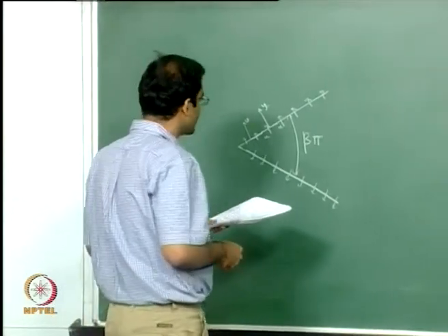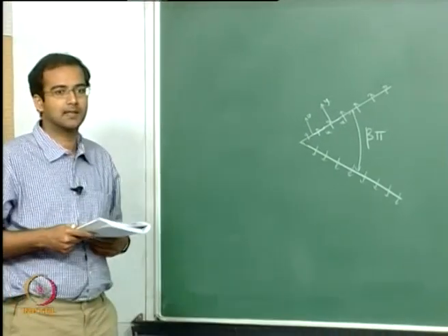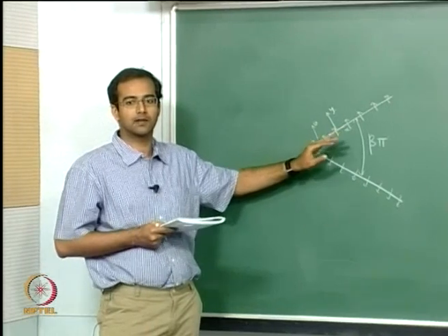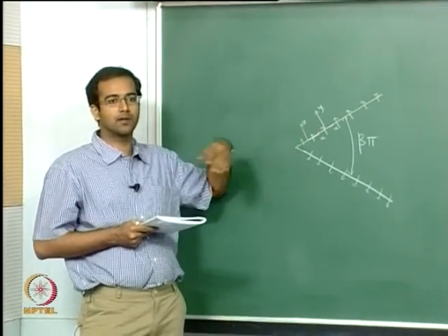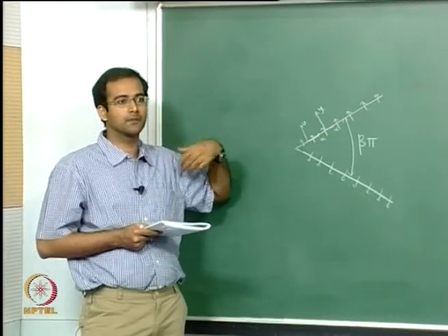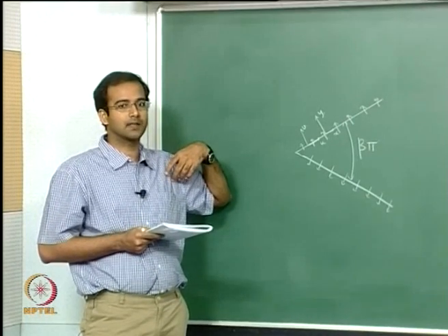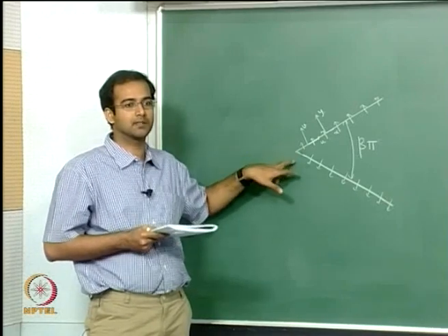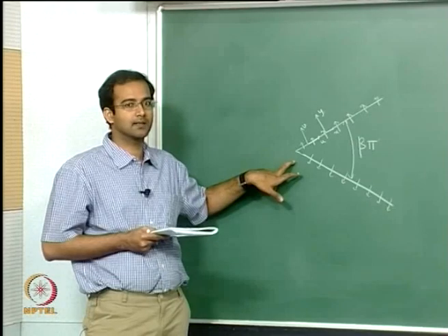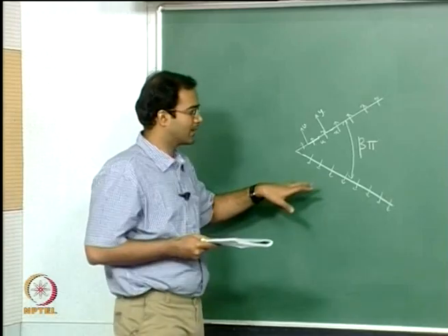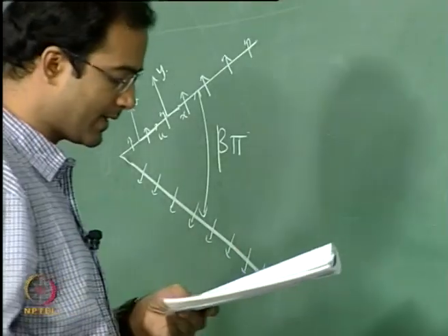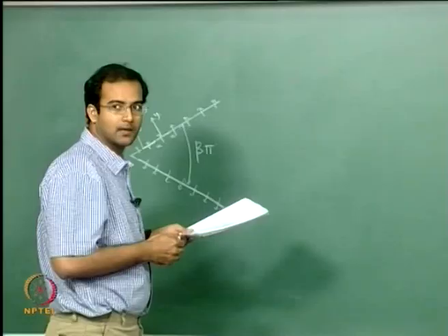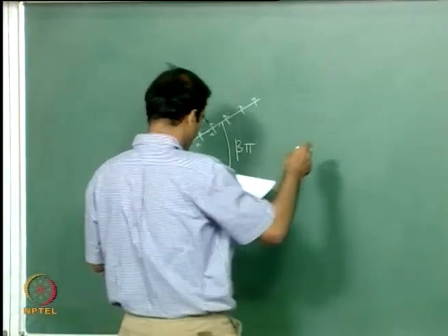The similarity equation that we derived in the last class is still valid because the boundary condition is not going to change the similarity equation. What we did was simply substitute for u velocity, v velocity, and also all the gradients and derivatives in terms of the similarity variables. So that is still going to remain the same, and therefore the similarity equation for Falkner-Skan solution is still going to be valid.